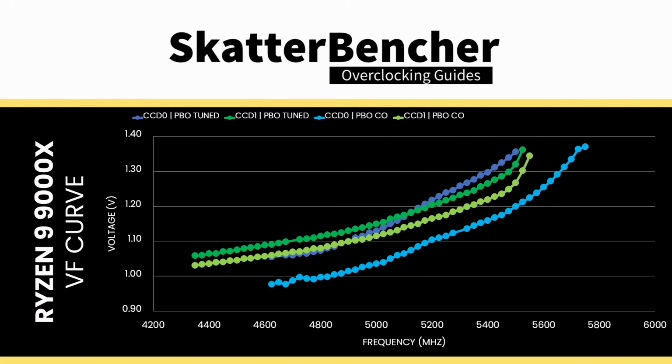Moreover, the frequency is also boosting higher. The highest frequency with all cores in the CCD active has increased to 5750 MHz in CCD0 and 5550 MHz in CCD1. These higher frequencies are now possible because our curve optimizer undervolting pulled them below the voltage threshold.